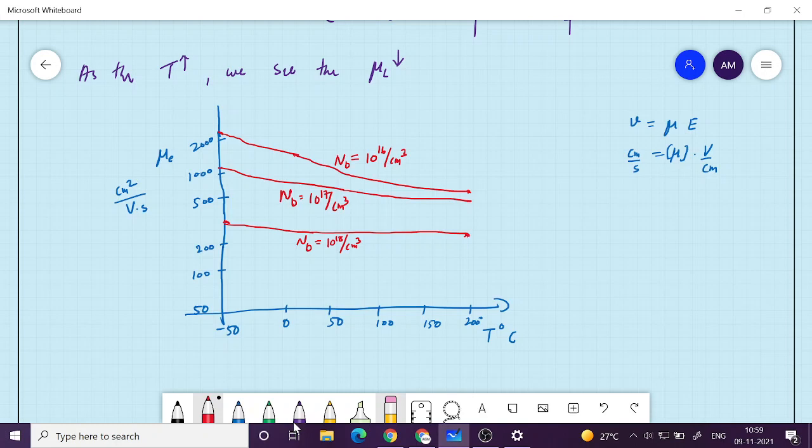So as you increase the impurity concentration, definitely you are creating more such centers of scattering. Scattering centers become more as you increase the doping concentration. Okay, but as you decrease, you see the contribution from impurity scattering reduces, because the impurities are very, very far apart for low doping concentration, and as a result you have much lesser contribution from there.